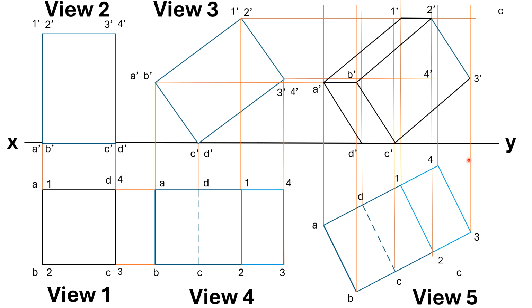And now I need to identify the hidden lines. To identify the hidden lines, I will first see the edges. So this is D4. D4 is one of the hidden lines. So D to 4 is a hidden line, and 4 to 2, and one more, 4 to 3. So this is another hidden line, and you can see it is above this line.